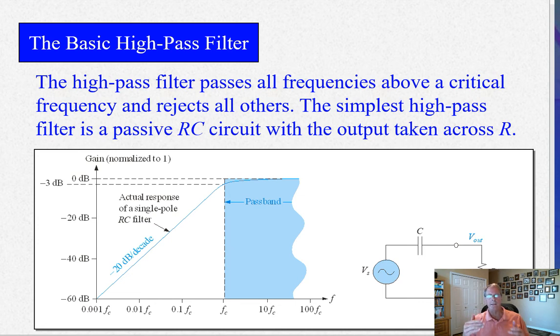And the way that I like to solve these problems is to take all the capacitors and short them all out, replace them with wires. That'll simulate a high frequency signal going through the circuit. And if you still have an output when they're all shorted, because the circuit becomes very simple, and we'll see this probably next week when I explain some more complicated circuits, you take a look at the circuit and either there's a signal out there or there's not.